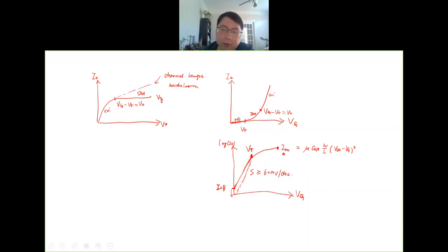And then for the off current, one more thing. Okay, I just realized we need to consider one dependency of the off current. That is VT. So if you shift the VT to the right, and you don't change the S, then you will have the same slope. Again, that means the off current will decrease. You see the VT increase, off current decrease. So you can use this plot to visualize how the off current changes if you change the VT, if you change the subthreshold slope.